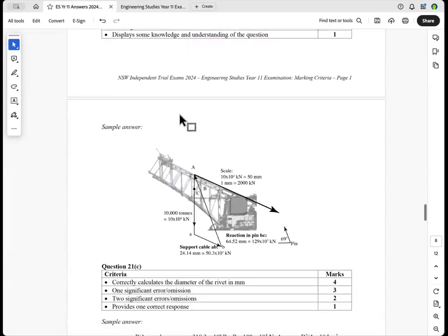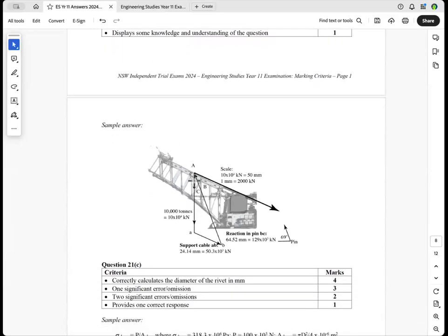So this is the solution here. So there's the weight force going through the center of mass. I was pretty pleased. Quite a few of you used the 3-force rule. But unfortunately, some of you just left it blank. And so you know that you produce that force on by the principle of transmissibility. You produce that force on. Where they join, there's your point of concurrence. And that's where this force in the pin will go through. So you've got your 3 forces there. Use Bow's notation.